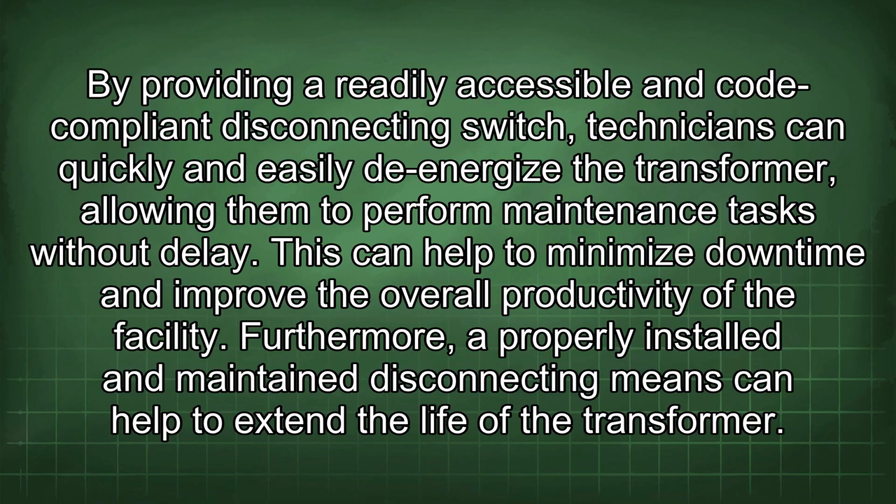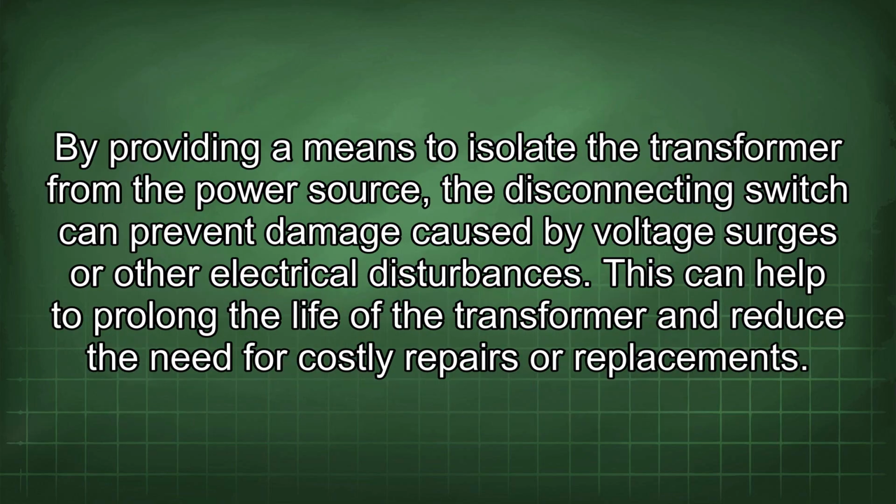Furthermore, a properly installed and maintained disconnecting means can help to extend the life of the transformer. By providing a means to isolate the transformer from the power source, the disconnecting switch can prevent damage caused by voltage surges or other electrical disturbances. This can help to prolong the life of the transformer and reduce the need for costly repairs or replacements.